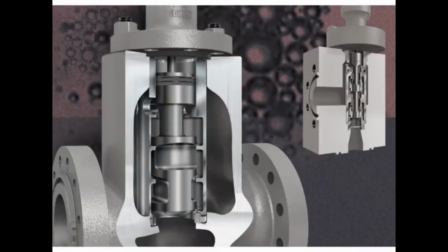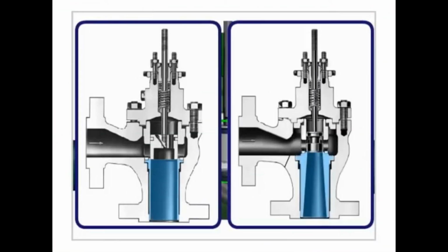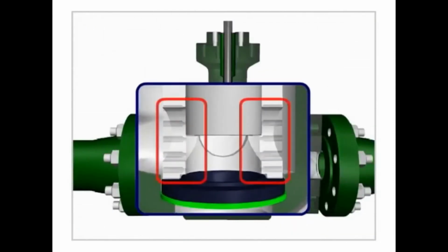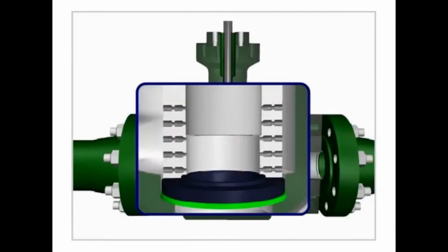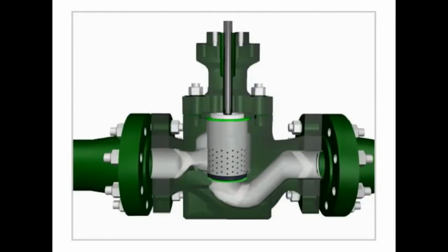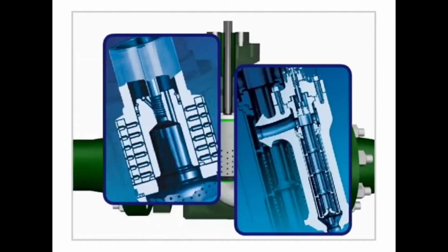Cavitation damage can often be reduced or prevented by using the proper components. Valve liners are constructed of hardened materials to protect the valve body. Pressure staging keeps the pressure from falling to near a liquid's vapor pressure, which helps prevent vapor bubbles from forming. Pressure drops are staged by the use of expanding nozzles or expanding flow areas.